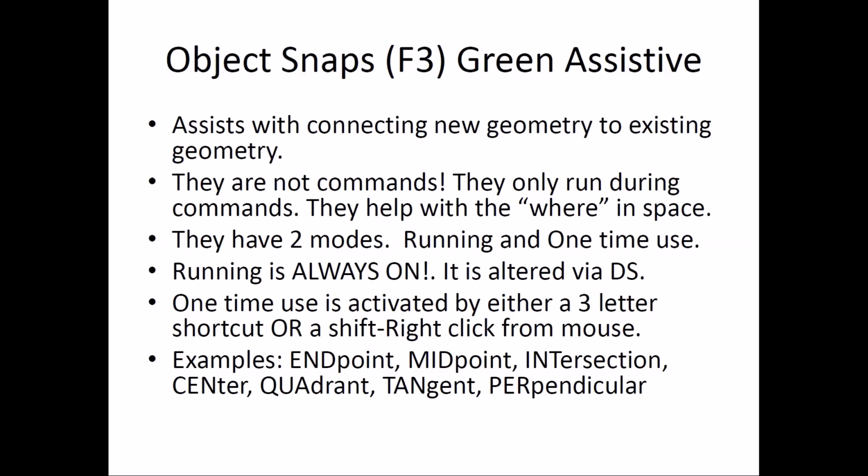Object snaps, they're not commands. Very important. Okay, object snaps are not commands. They only run during commands. So they're in between. They run during that period of where. When AutoCAD asks me where do I want to put something, okay, that's their purpose.